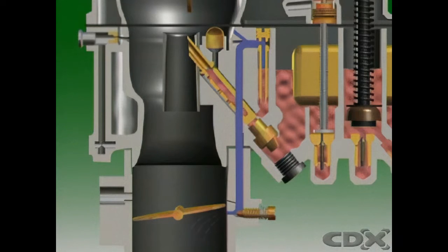The throttle valve is almost closed, so airflow through the carburetor is very small. The action of the piston creates a low pressure area below the throttle, and this is concentrated at the edge of the throttle valve as the air passes the idle port.